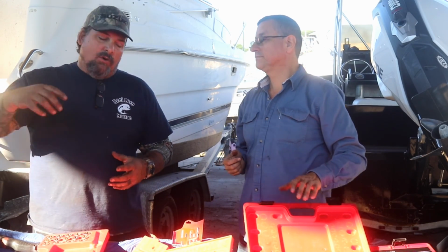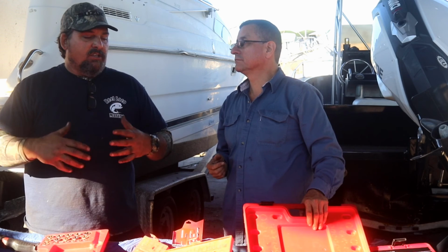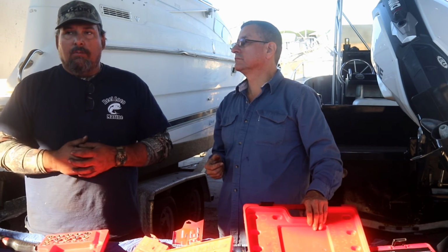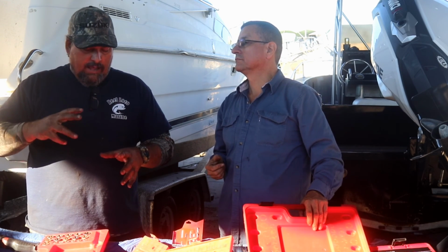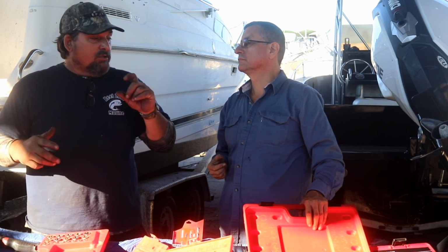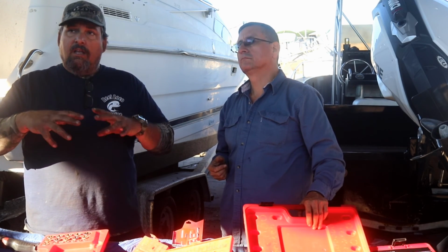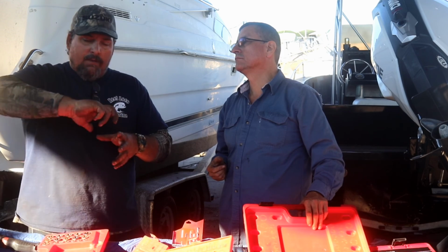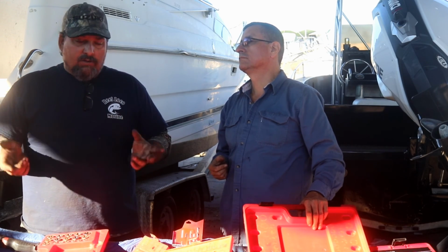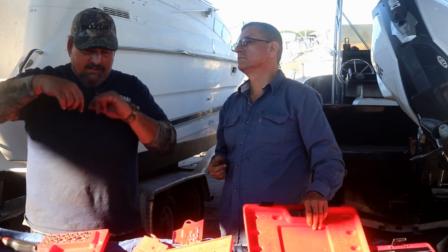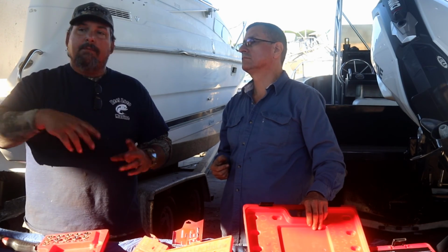And you return back and return. Because what happens is you don't want to break that tap in there because it's hard steel, just like a drill bit. So it's important that when you're doing that, I usually use some kind of penetrating fluid just to help it, and then you just go back and forth until you go all the way in. Once it goes all the way in, you take it back out, I usually clean the tap, and I'll do it one more time to make sure everything's good.